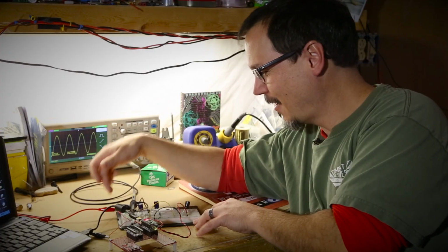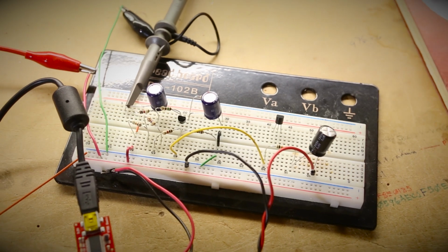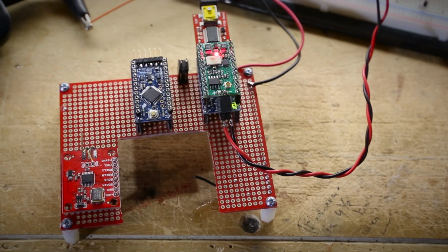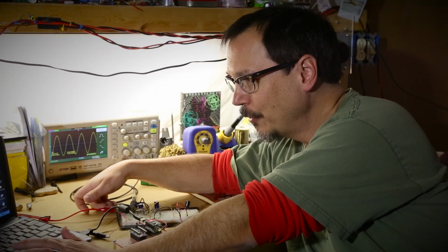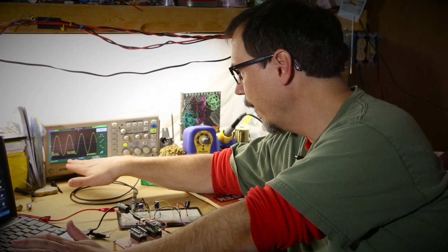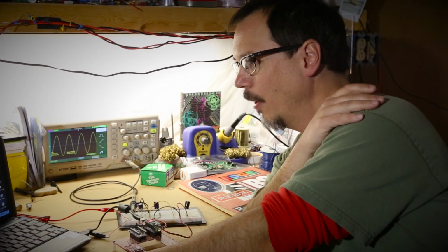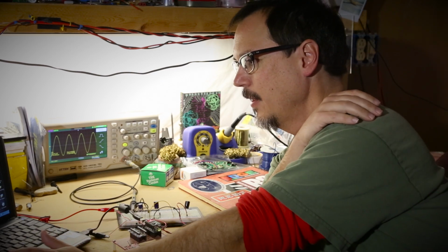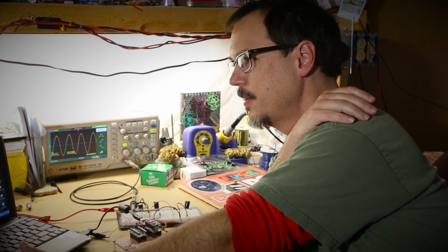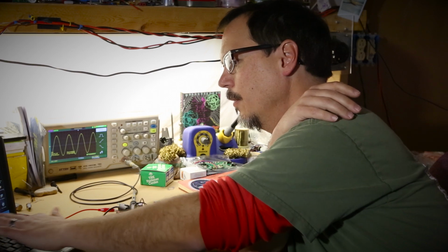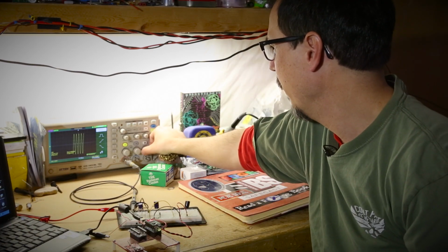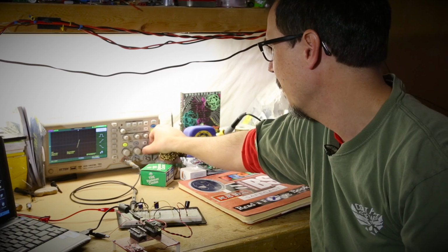So I've got my circuit set up on a breadboard. It's nothing really special. It's a whole bunch of resistors poked in holes and a transistor. Here I've got my signal generator, and I've got my terminal open, and I got my waveform here. Now, one of the things I wanted to show you is what kind of performance you can get out of this. Right now it's running 5 kilohertz. If I take it down to 50 hertz, ooh, the waveform disappears, which is kind of what we expect.